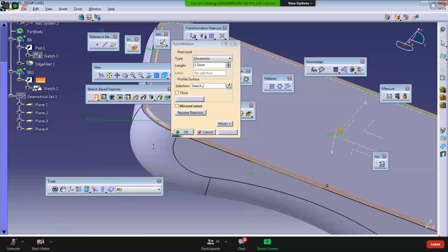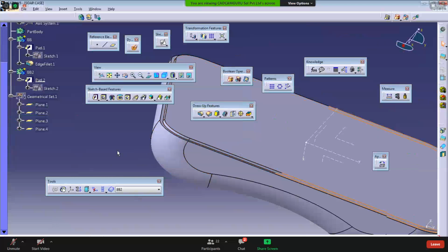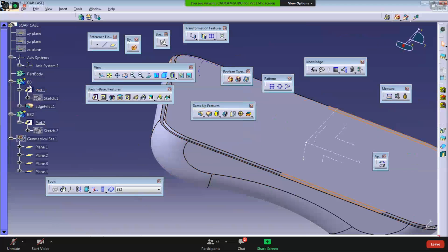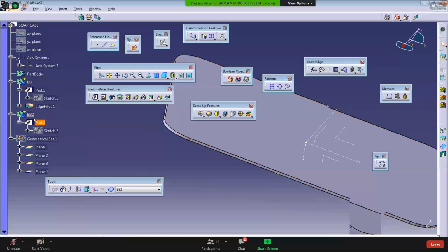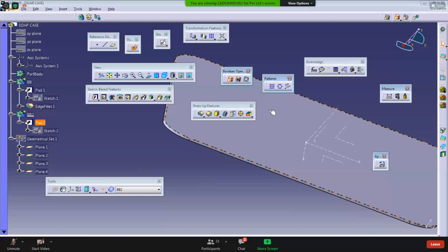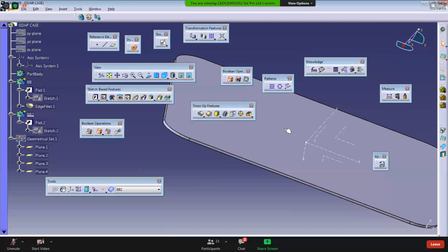We can see that. Okay. Now this body is different. We can see that this is a different body. Okay. Now you have to add this body in this base body. How to add? Simply use the Boolean operation tool. So to activate the Boolean operation, just drag this option, Boolean operation tool, and use the first command in it. What is that? Add. Just expand this drop-down list. This is the first command, which is the add.